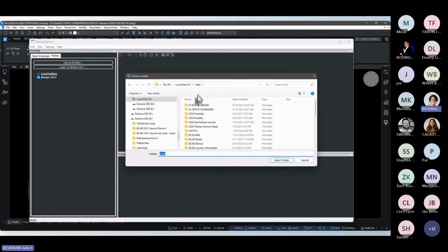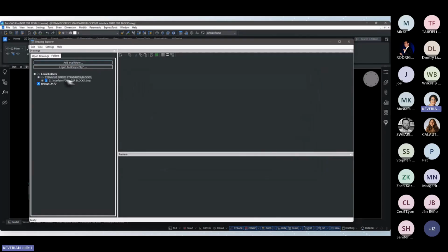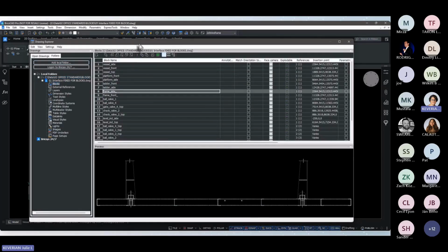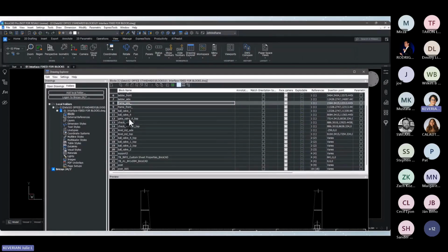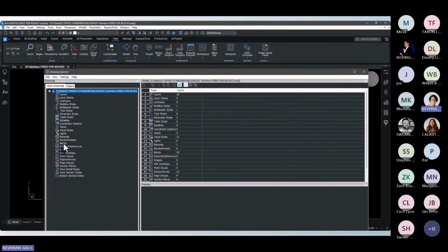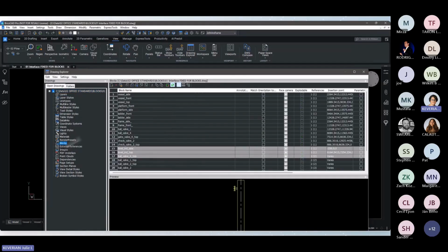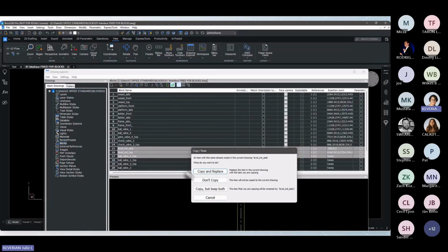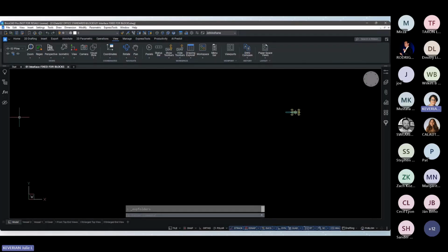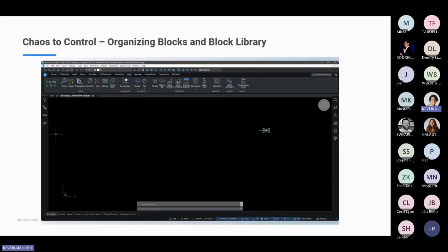Then use the Folders tab in Drawing Explorer to add a local folder. And this local folder is your Office Standards folder. This setup allows you to browse and access drawings that are not currently open, making this an ideal solution for building and maintaining a standards library. Now, yes, I do still have the file open, but that is not necessary. You can simply select one or multiple blocks to copy into another open drawing, or simply right-click on a block to insert it directly. Now, a bit later, we're going to talk about how to use the Drawing Explorer for other style content as well.